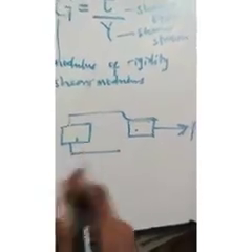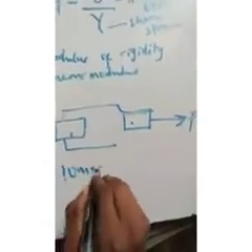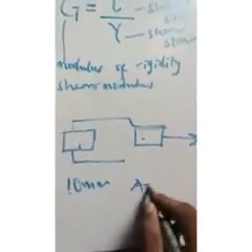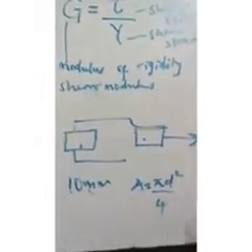If you are given a diameter, let's say 10 millimeter, you can find the area. The area is equal to pi d square over 4. Then you can substitute this inside and you have your answer. In different cases, if you want to find half of it, you can define it, but it's not really important. The main important thing, the summary of everything, is that the formula for the stress is originally load over area. So you can have this as Fs over area.